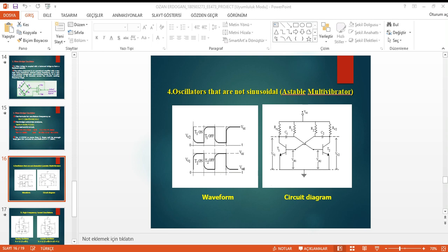The circuit is configurable for single or dual supply operation. Essentially, only the voltage levels of the waveform are different in single and dual power supply modes. Charge and discharge times are the same in single and dual supply modes. Consequently, the period or frequency is the same in the two modes.